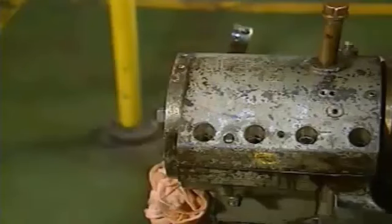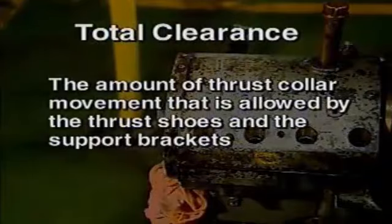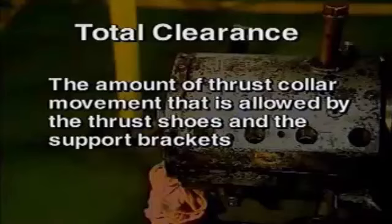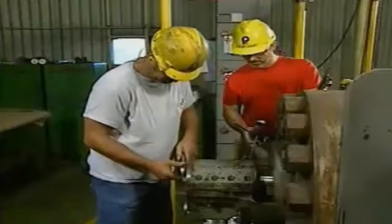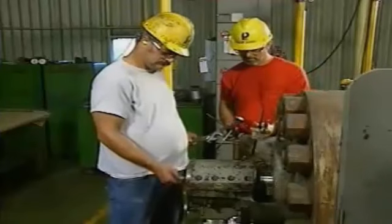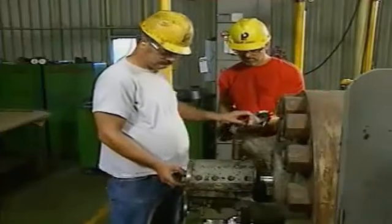Typically, the first step in thrust bearing maintenance is to take a thrust reading to measure total clearance. The total clearance for a thrust bearing is the amount of thrust collar movement that is allowed by the thrust shoes and the support brackets. Thrust readings can be taken with feeler gauges or wedge gauges, but these mechanics will use a dial indicator.